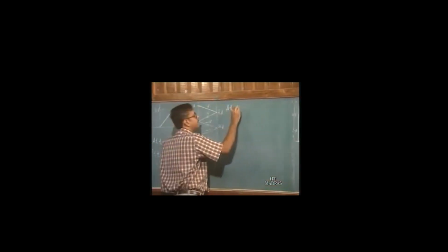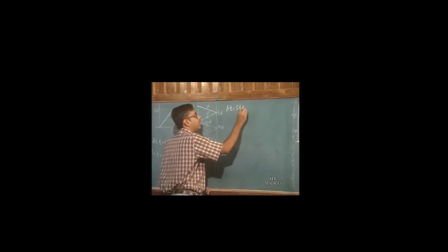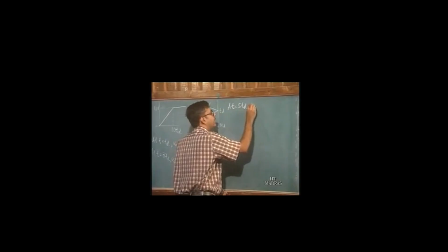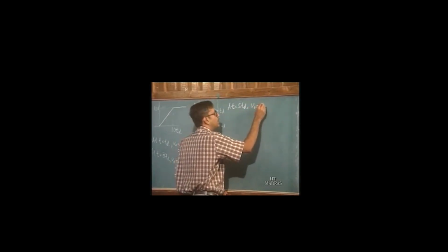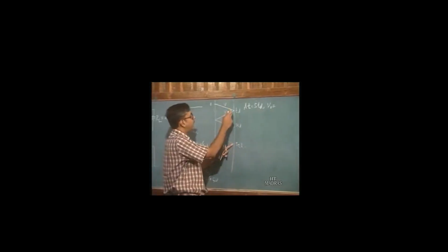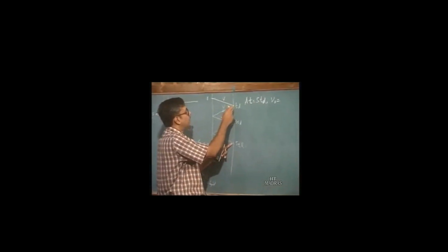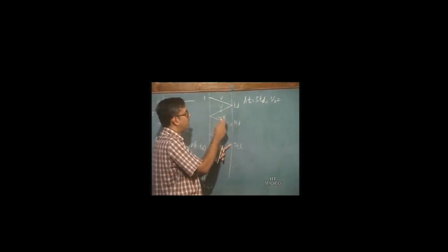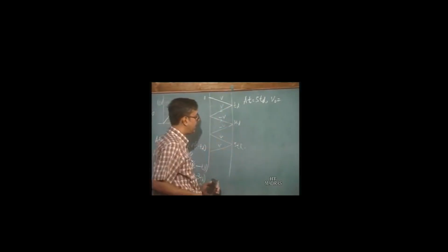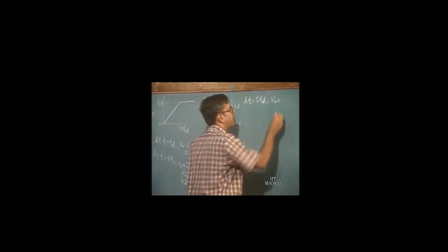Now at T is equal to 5 TD, you have again V output, which is going to be twice the voltage which started off TD before, minus twice the voltage which started off 3 TD before, and twice the voltage which started off 5 TD before.